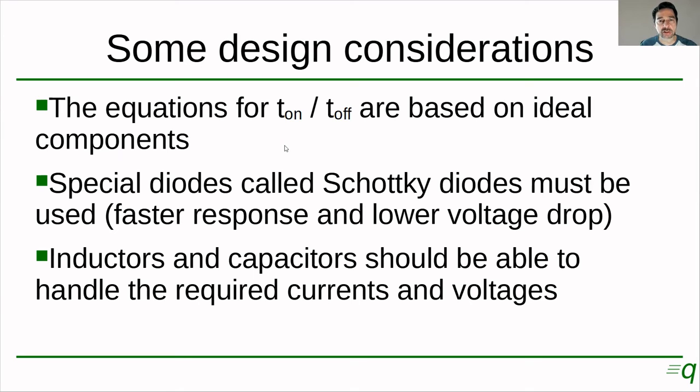The regular diodes that we studied for rectification are not good for switching power supplies for a couple of reasons. One is the response time. We need something faster. And we also need to minimize the voltage drop as much as possible.